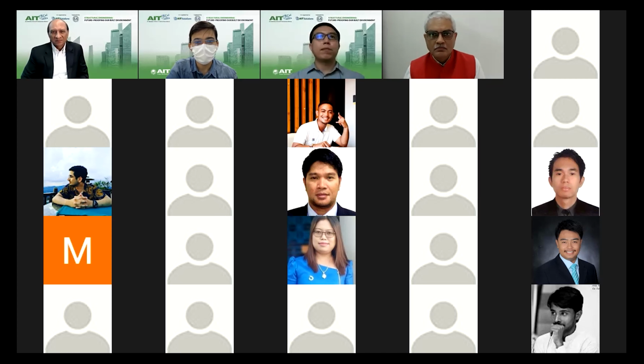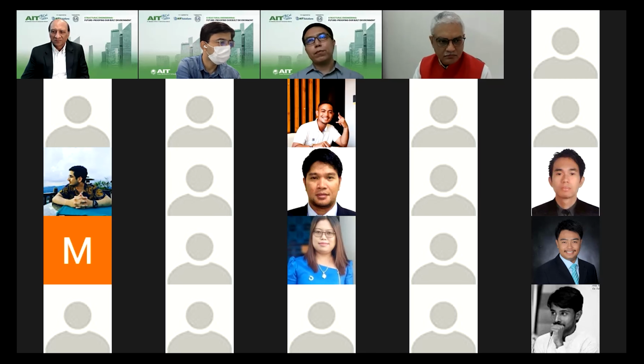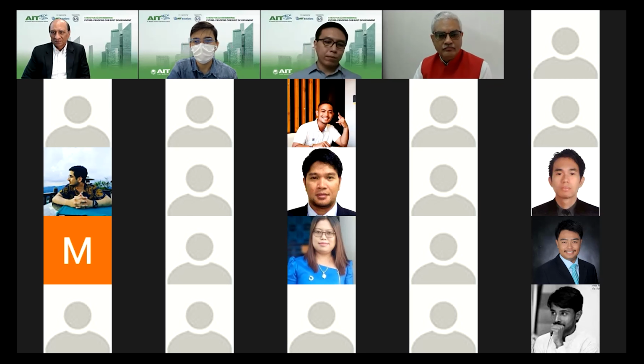Yes, Mr. Rao. With regards to the modeling, many people prefer columns with the lump plasticity model, the PMM hinges. You can also use fibers. There are benefits and drawbacks to both of them. With the fiber, you get the benefit of not having to model your backbone relationship, so you save time on that. You let the fiber define your behavior.